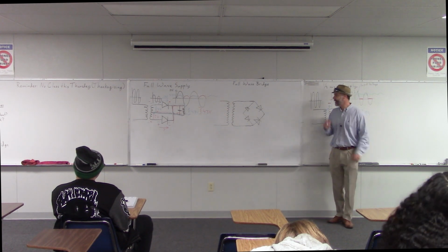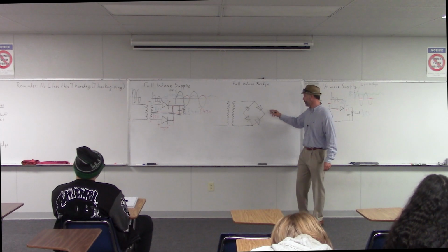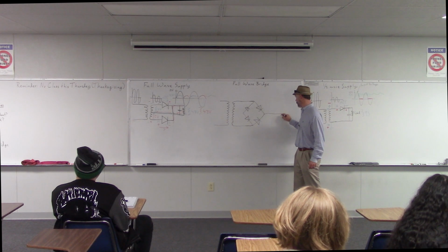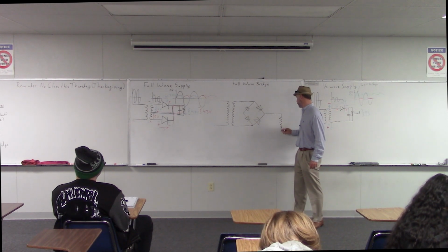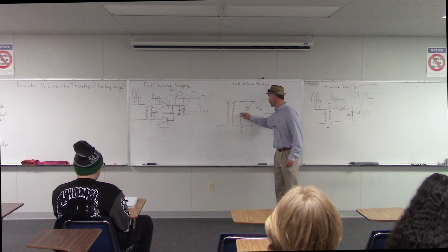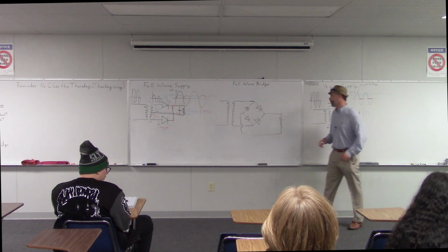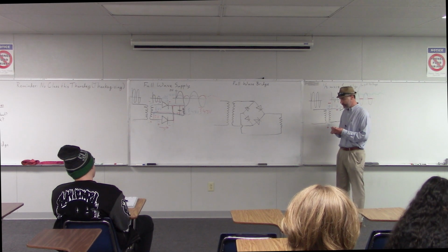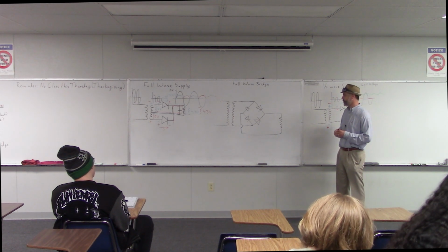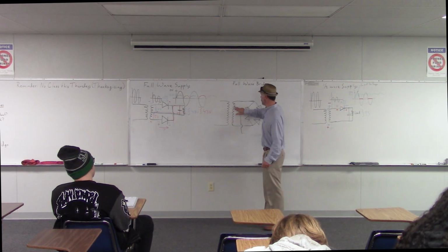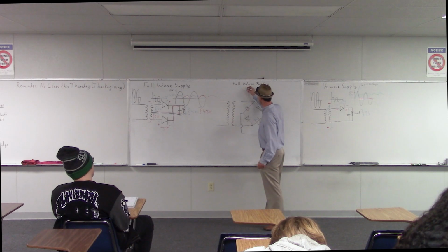All right. So that is the rectifier, and then again, that feeds out to our load. So our load would be over here. So that's a full wave bridge supply. So let's talk about how this works. So again, we can assume that the signal coming out from our transformer here is 10 volts peak.